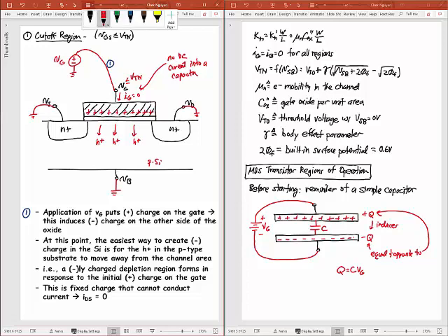And the types of electrons they're going to leave are, I guess I'll keep using red, static negative charge, right? So it's just like the p-n junction. When I move the majority carriers away from that junction, what's left is the opposite charge, right? So I move these positively charged holes away, I'm left with negative charge there, and it's static charge. It's a depletion region is what it is. Okay? So when I have positive charge there, I effectively have created a depletion region that's, say, that thick there. Okay? You also know that between this N plus and P junction, I have a depletion region, right?